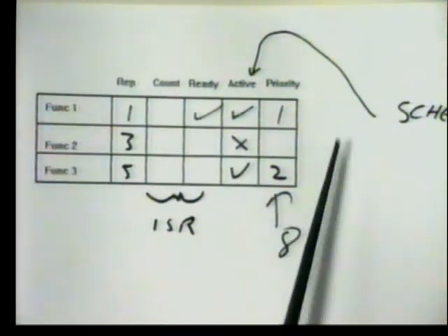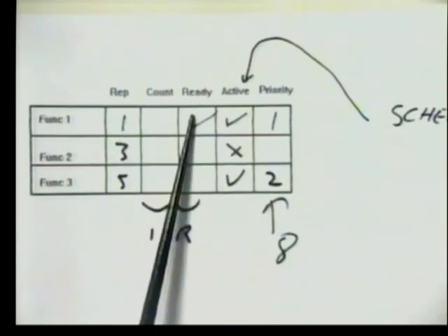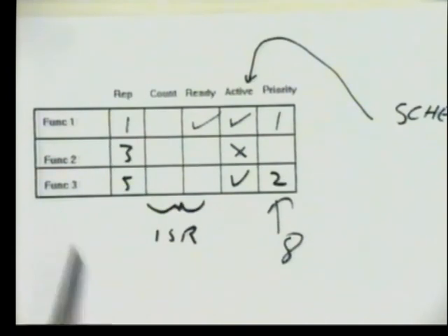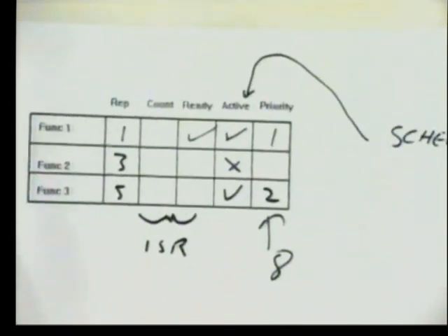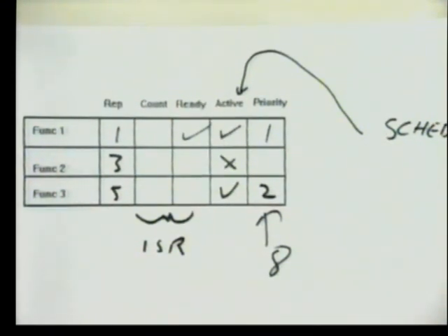If it's more complex than that, then perhaps you want to look at a simple scheduler arrangement. But the most complex scheduler you're ever going to come across is something as simple as this. This was just a byte array. The whole thing was done in about, what's this, 1, 2, 3, 4, 5, we had 8 tasks, 40 bytes of data memory used to implement the whole operating system. And all the scheduler did was run down it. It was just an if this, then else. A very simple bit of logic, just running down the task list and running the function that needed to run. Very, very simple, very easy. Don't be afraid of operating systems. Put your thoughts and energy into thinking more about interrupts.